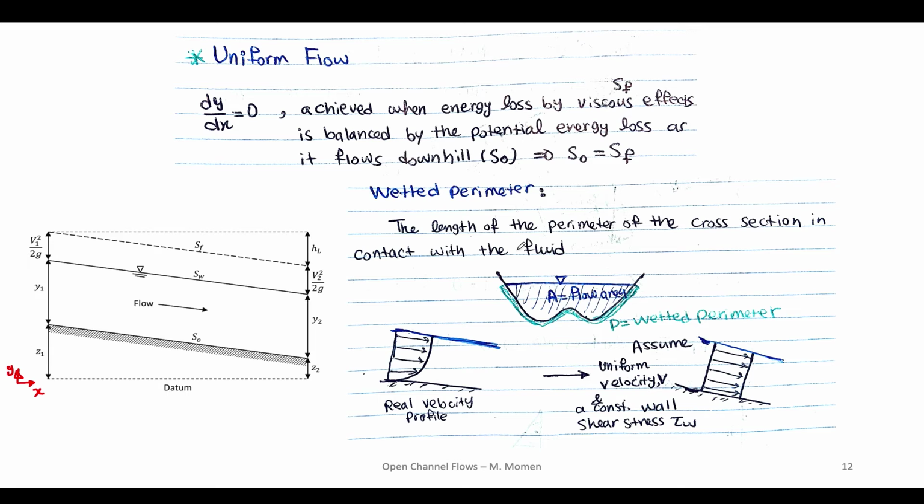As you know, the channel cross sections can have different shapes, and in order to make a general formula for any type of cross section in channels, for instance, we saw both rectangular and triangular channel types, we make a definition which is shown here as the wetted perimeter.